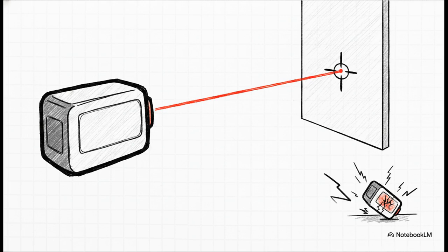You absolutely must calibrate these devices regularly. Because they're digital, they're prone to internal malfunctions and something called electronic drift. In construction, your linear measurements generally need to be accurate to within 1 millimeter. So if you drop your laser, or if environmental factors knock the sensor out of alignment, well, that 1 millimeter tolerance goes out the window real fast. And honestly, so does your material budget.